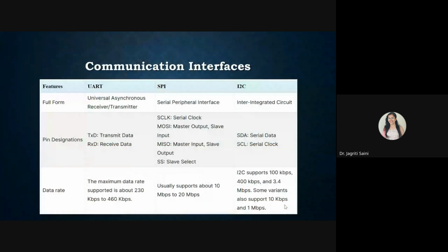For instance, with the communication interfaces, the most commonly used one is your UART communication. The initial two options I have given you are the analog and digital sensors. After that, the third option you have is UART communication, with TXD and RXD lines, if your sensor defines this preferably on the chip itself. As I told you, on all the sensors, on the pins themselves, it will be written how you can connect it with the microcontroller on the other side.